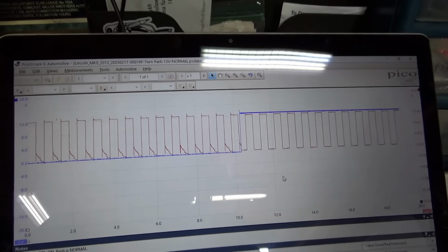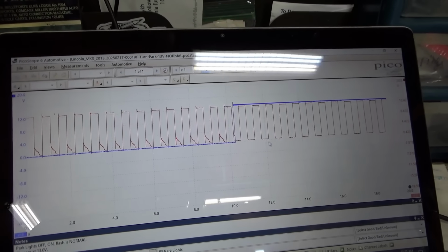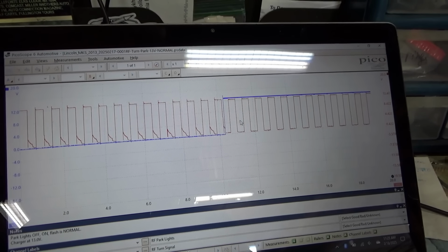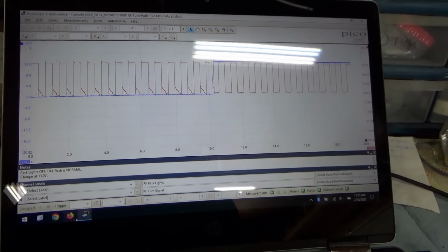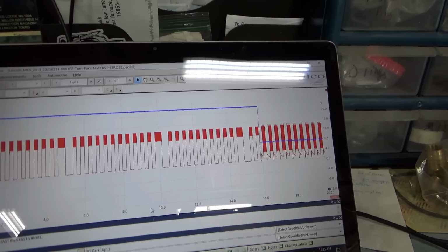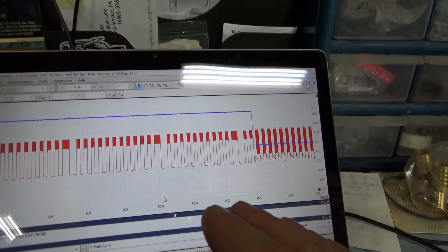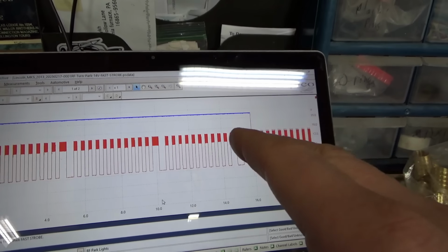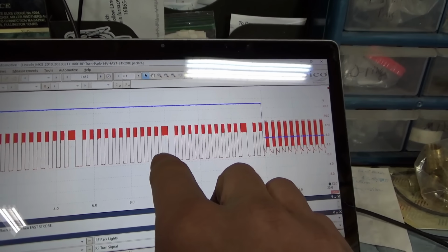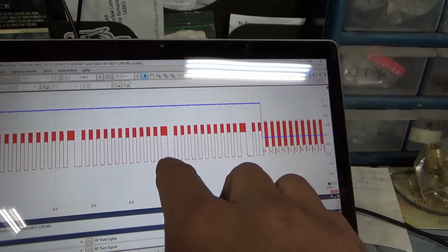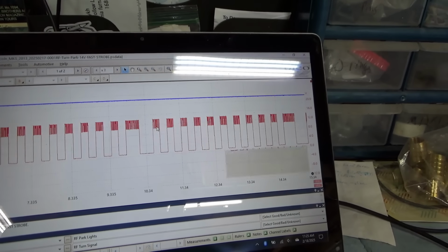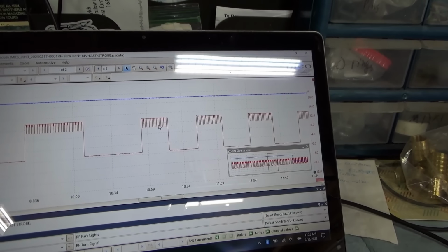So interesting, right? But visually, if you're just looking at the turn signal, you wouldn't say anything's wrong here. The cadence doesn't change. Nice, normal, slow, steady flash. As we bump the charger up to 14 volts, things really start to fall apart. So today, unlike yesterday, even with the parking lights on, it was still flashing fast. Most of the time, sometimes it would go back to its slower cadence for like 1 or 2 flashes.